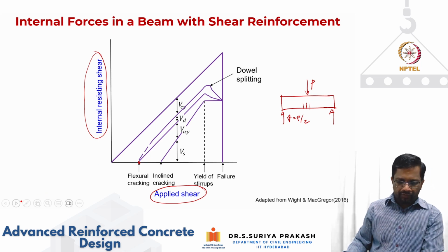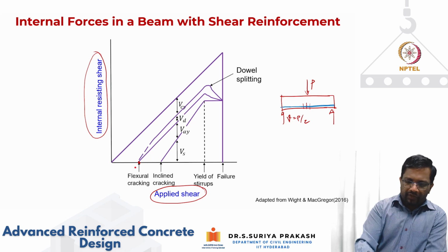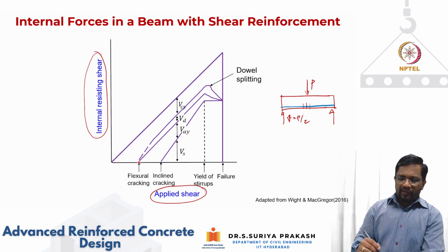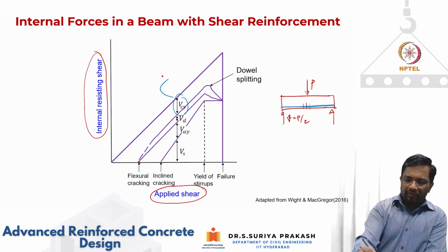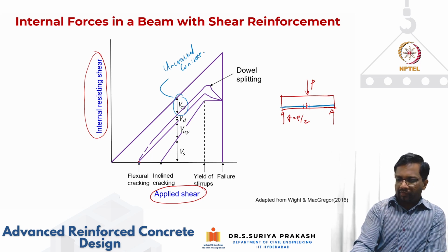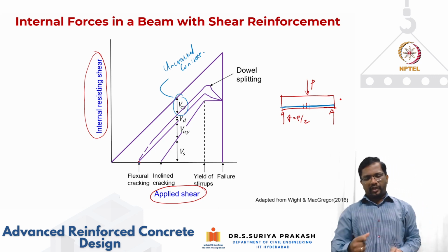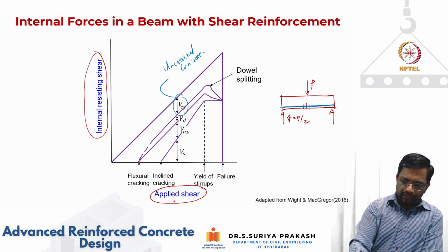Then you also have some reinforcement, let's say tension reinforcement is there. Now the flexural crack that forms, the moment it forms, you are cracked. Before it cracks in flexure, the entire contribution was from your uncracked concrete. Then the moment the flexural crack forms, the dowel action starts kicking in, because now the crack is resisting the applied shear, right? So the dowel action will start increasing.